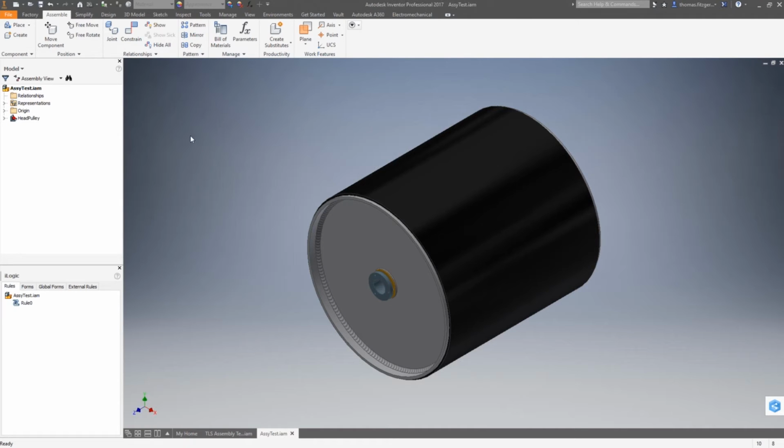Static files, obviously, you want to build your extrusions and your revolutions first. Give them logical names. If you're not aware of this, guys, at any time, if you slow double click on a feature or something within a model, you can change the name. You shouldn't have any spaces. It's best if you use camel case, which is nothing more than capitalizing each word. So change the name. I capitalize C, T, and N here, and that is what we use as a delimiter between the words.